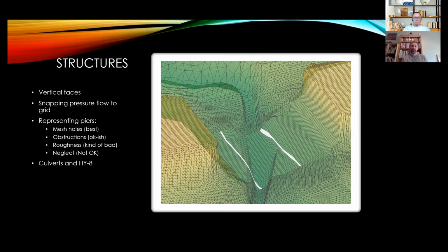We also need to make sure that we're capturing the high point of the road and other hydraulic controls in the topography. Pressurized bridges and culverts present their own unique challenges, so we've got items to check on our sheet with regards to these features.